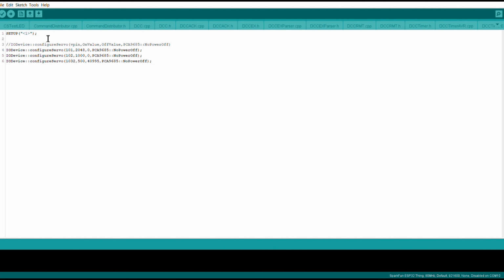This first line, if you're interested in that as well, I'll cover it since I put it in. This turns track power on at startup. So every time you power up the DCC-EX command station, it will turn on track power. If you don't want that, if you want to manually turn on track power, then just don't put that in your setup file. Below that, these are the commands for defining LEDs in DCC-EX.